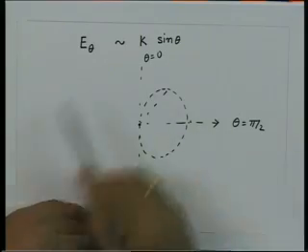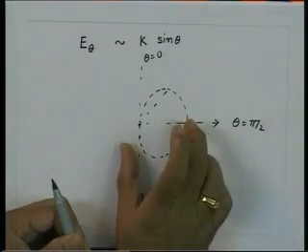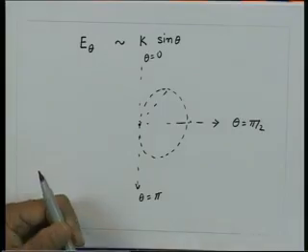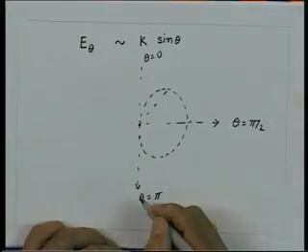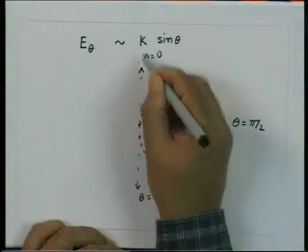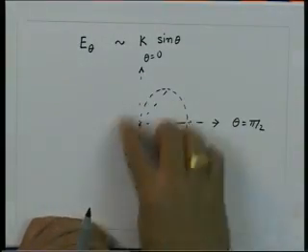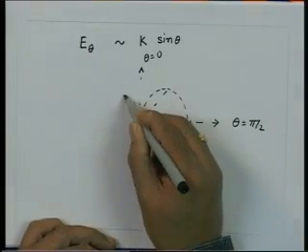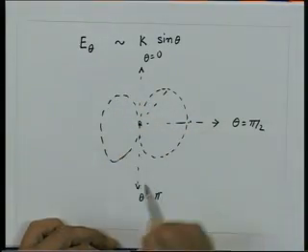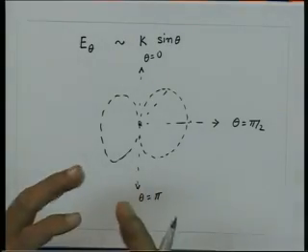And now, since it is circularly symmetric, I take this pattern and revolve it around this axis, which is the axis of the Hertz dipole. So, around this line, which is the z axis, if I take this pattern and revolve it, I will get a 3-dimensional figure, and that is what we call the radiation pattern of the antenna. So, if I visualize this in 3 dimensions, then the structure would look something like that.